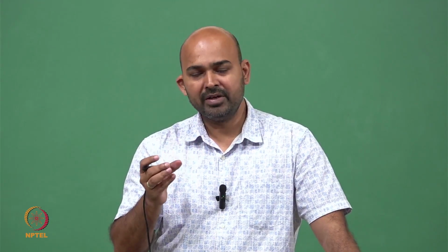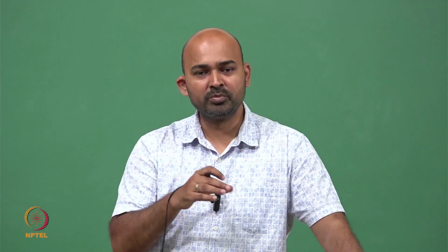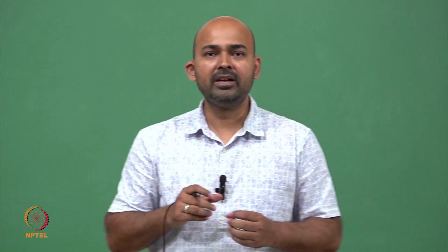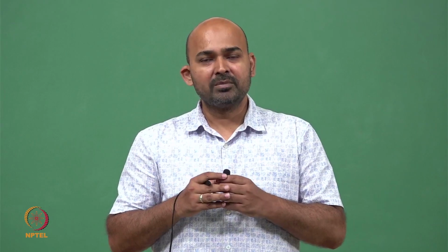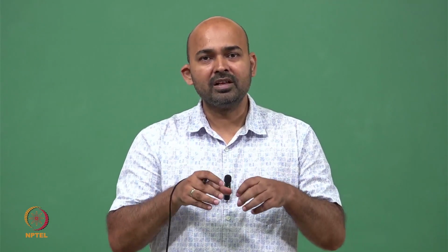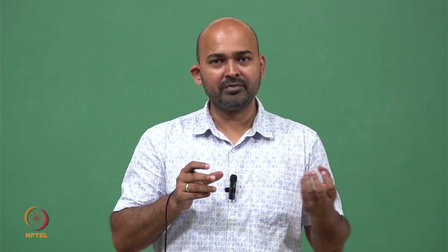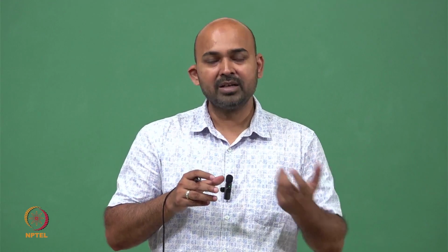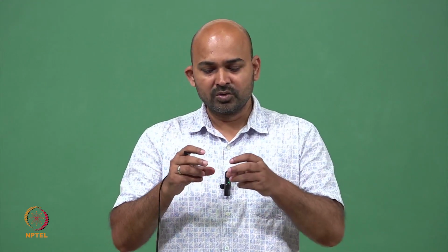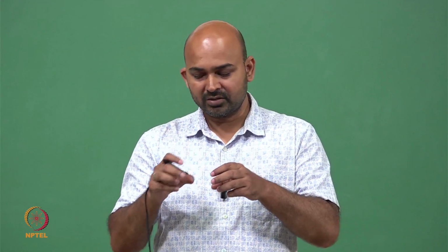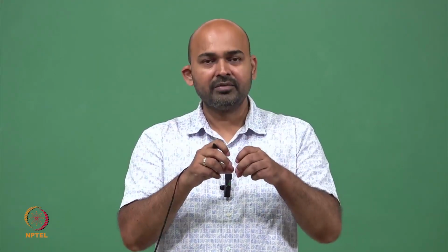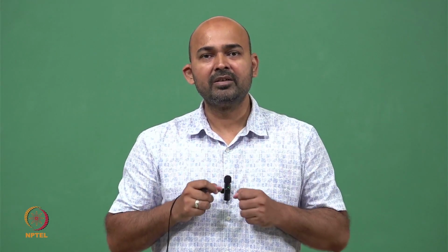So we want an amplifier stage immediately to boost the signal. Sometimes we want it on the chip itself, because if we use a discrete amplifier, the signal will fade away when traveling from the magnetic material to the amplifier. So sometimes we want the amplifier very close to this magnetic film.